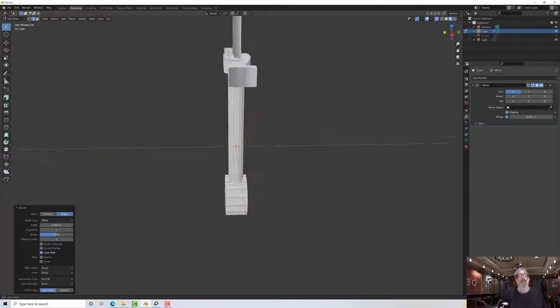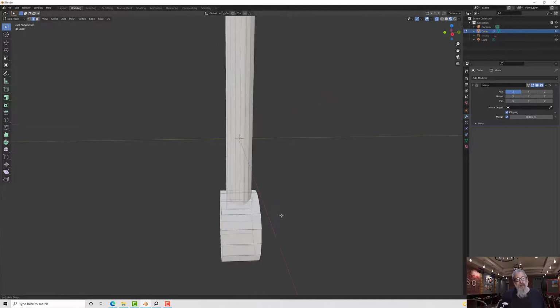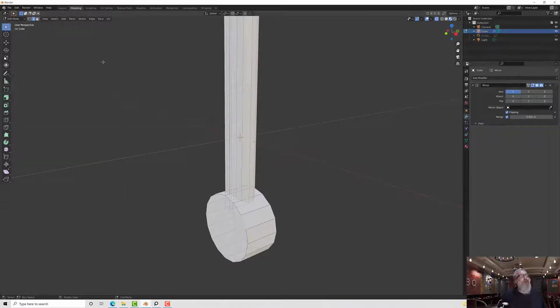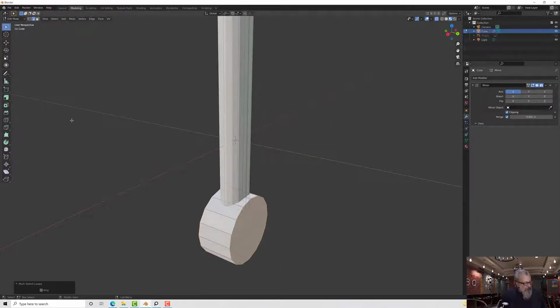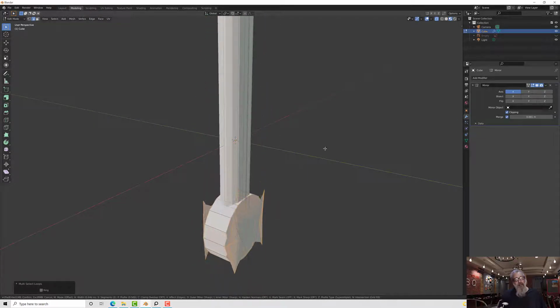I do want to bevel a few more things, so let's bevel down here first. So I'm going to select these two edges on the front and the back of the pommel, and then we'll go to edge, not edge, sorry, select and select loops and edges, and then we'll bevel those. So it's Control B and then find our direction. There it is. Sometimes it's a little bit crazy and doesn't really want to behave, which it doesn't appear to at the minute.